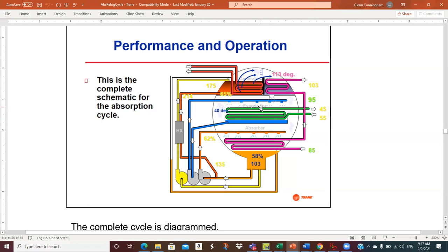So the liquid that vaporizes, again, migrates its way down to the absorber and gets recombined with the lithium bromide. The water that doesn't evaporate falls down in this tray, and this pump just keeps pumping it up, spraying it out on these tubes. So eventually, any particular water molecule will get evaporated, but we continually have this water flow down here. So this is basically a steady state situation. The capacity can change, and so there are some transients, but generally speaking, you can think about this as a steady state process. So all of this is low pressure down through this region.